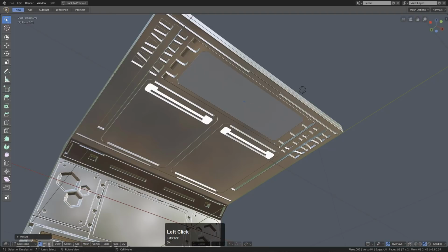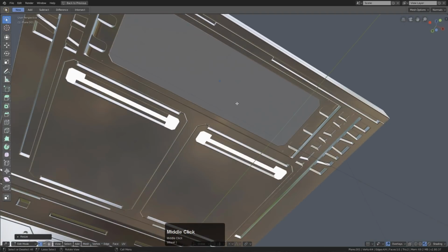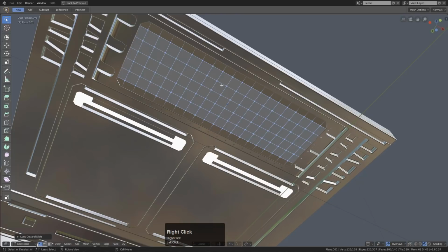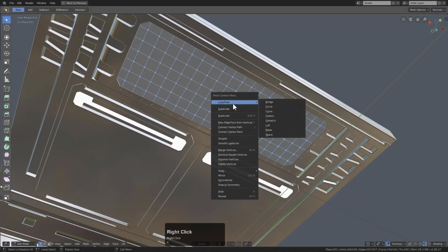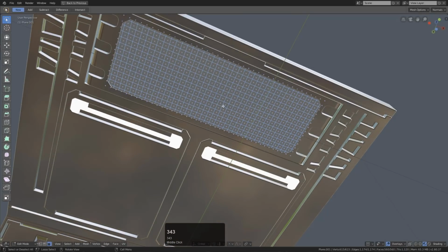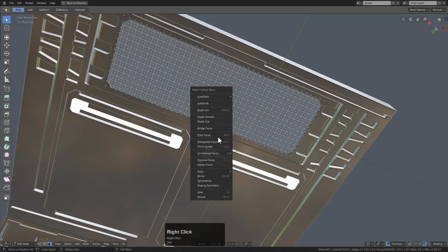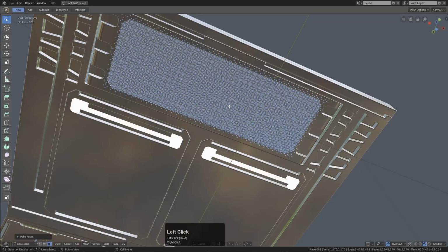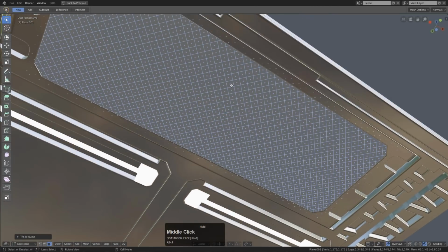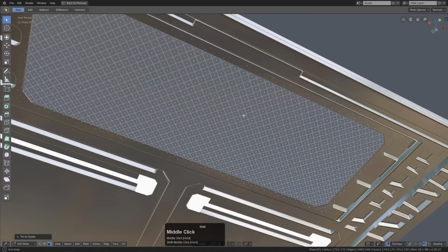Just examine it, and that is pressing Alt P and Alt J. But first we got to use Control R and just roll some loop cuts in here. We want to roll some more loop cuts so it's like a square shape everywhere. And we're going to subdivide that because why not? Now in face mode, I'm going to right click and see if poke's in here. Hey, poke is in here. So never mind. We're going to poke these things. We're going to press Alt J, which basically redirects the edge flow. So poking it and then redirecting edge flow.